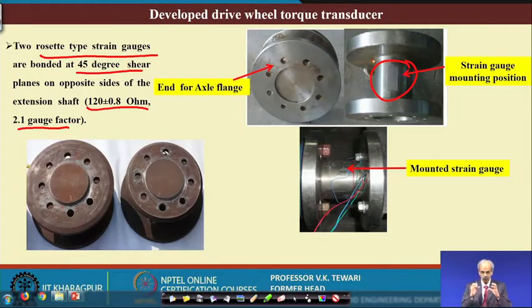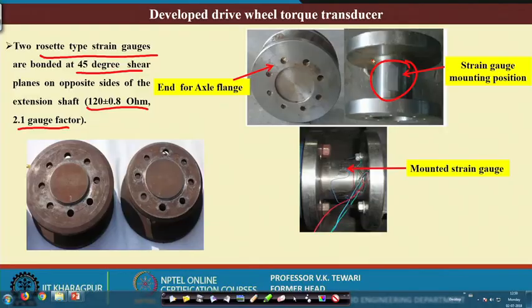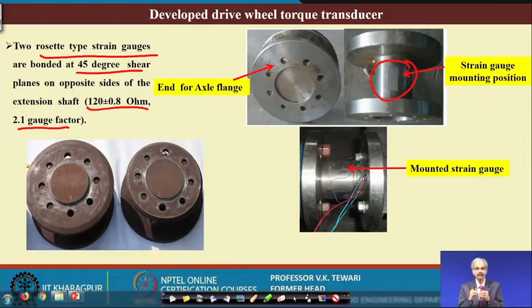This is the secret. We did a lot of experimentation, trial and error methods, and also theory behind this, such that we are in a position to get the position where we will get maximum response the moment we put the strain gauges. So, we could design the locations where we mounted the strain gauges, to get a larger response of the strains experienced by this particular flange.